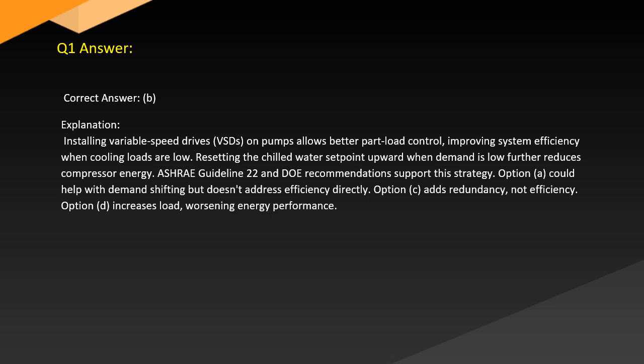Answer. Correct answer: B. Explanation. Installing variable speed drives (VSDs) on pumps allows better part load control, improving system efficiency when cooling loads are low. Resetting the chilled water set point upward when demand is low further reduces compressor energy. ASHRAE Guideline 22 and DOE recommendations support this strategy.